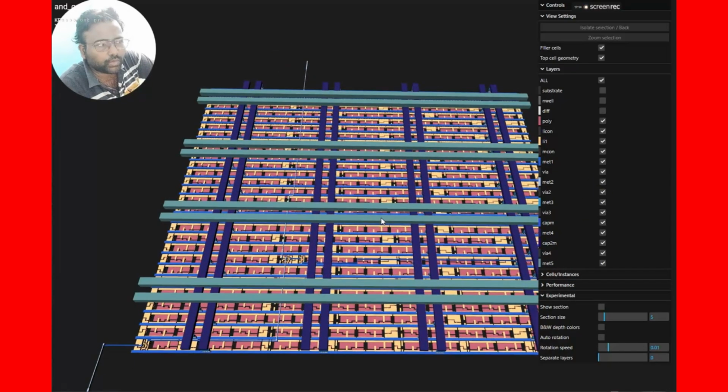See, converting Verilog to this is so simple in code. But if you do it with separate software, you need separate tools for synthesis, for KLayout, for the substrate, for preparing wires and the fabrication layout, like Magic, all separate software. It takes more time. But in OpenLane you just write a single config and use the flow command, and it automatically converts all the processes easily. So you can send it to a factory for fabrication. So much easier than doing a lot of work. This only supports 130 nanometer, not 2 nanometers. Thank you.